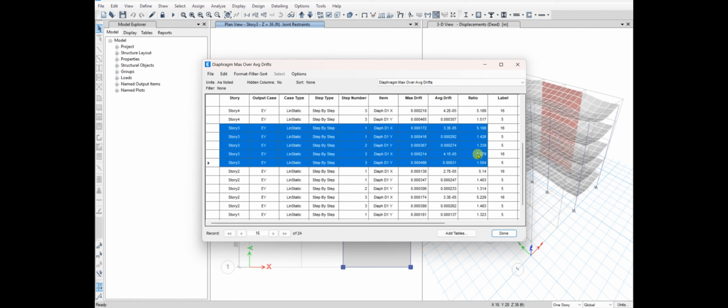Because under EY, in addition to displacement in the y direction, there is also a small displacement in the x direction due to torsion. So the software mistakenly checks delta x, which are extremely small, and ends up dividing two small numbers, two numbers close to 0, which produce artificially large values.